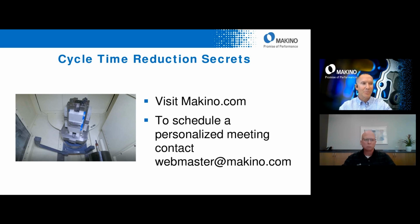There was a FANUC parameter 5001 that had a bit that had to be set. But in this case with M319, is there any consideration like that? No, it's standard M319. No parameter changes need to be made. As soon as it's installed, you start using M319. Great. Okay, that makes it nice and easy.